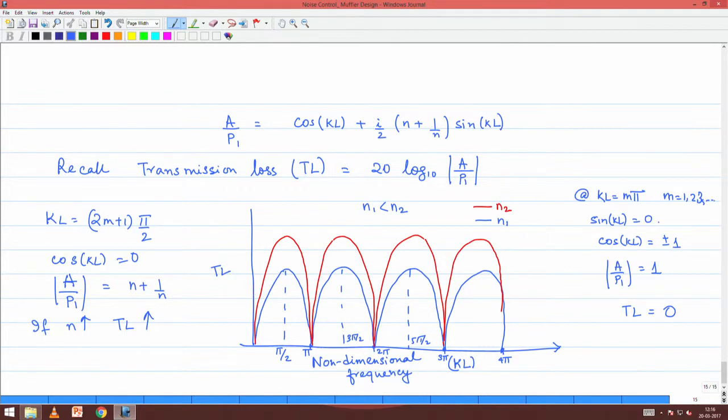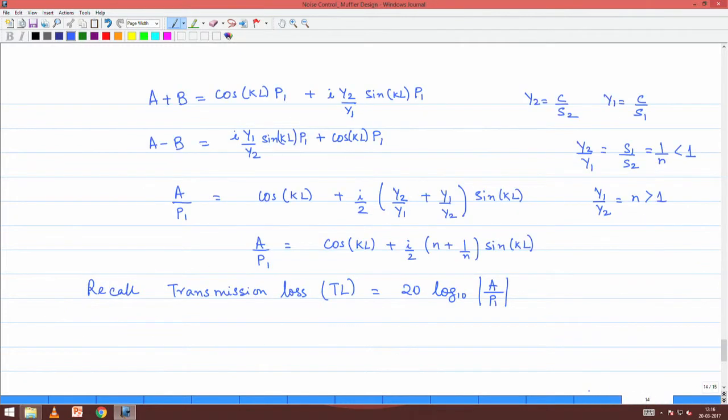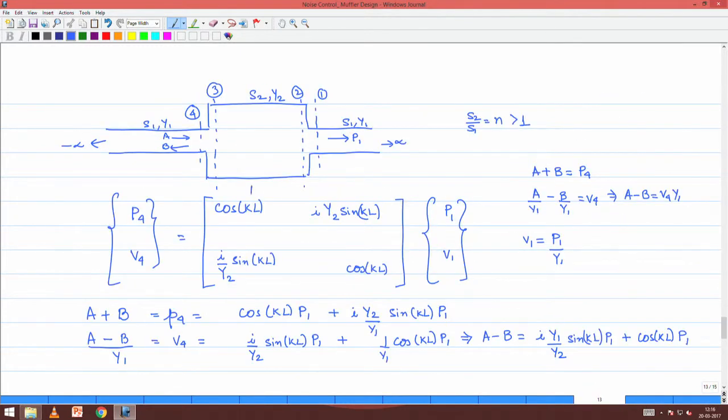Now, how do you make use of this fact in the design of exhaust system and design of muffler systems for exhaust? The answer lies in this fact: please understand that if your exhaust noise happens to show frequency content around these values where KL equals pi, then this expansion chamber muffler is useless. Okay. So, you should rather choose an L. So, remember L is a design parameter.